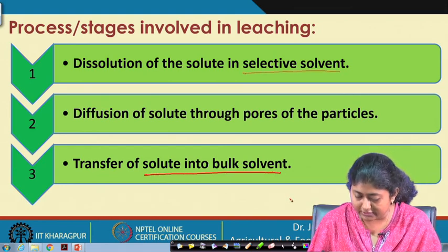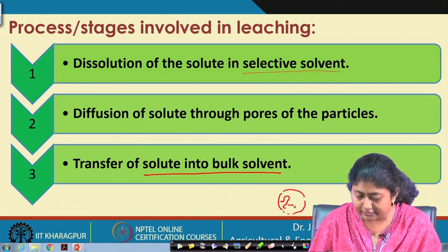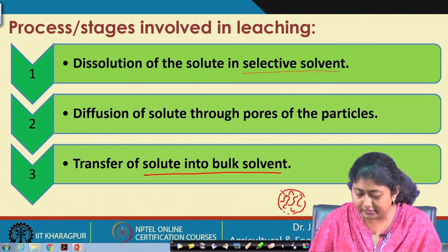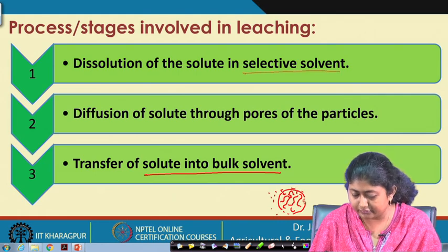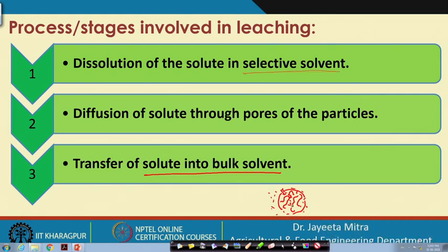Okay. Suppose we have the material, the micella, and there are pores through which the liquid comes into direct contact with it. The liquid has to first enter into the pores, then the solutes which are in some pockets, in the inner core of the material, will first dissolve, then diffuse to the surface and get mixed with the bulk liquid.